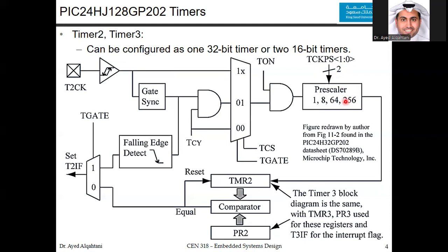and we will see them exactly in a few slides. Now, after you chose the clock, right now here, you choose the ticks, and you are getting the ticks as you decided. Usually we choose the internal and we put an appropriate prescaler value, and now you have the ticks right there.